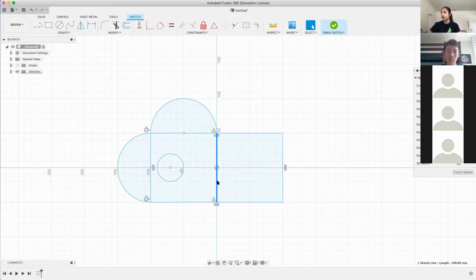So if I right click on the line here, you'll see it gives me this option, normal/construction. And if I click it, the line becomes dashed and the rectangle's whole again. And so this is what's called construction geometry. It's something that you draw into your sketch, but it's used purely as a frame of reference, a means to an end for constructing other geometry.